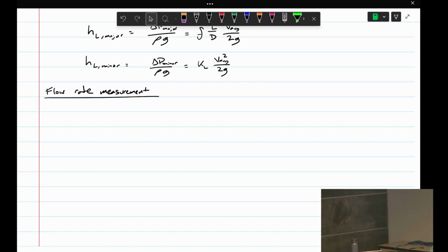Look at the drawings. So that maybe is the nominal case, when you're controlling this. A strain on different parts of the pipe. That's an interesting one. So that could maybe give you the pressure if you had a very good measurement. I think that might actually be used for pressure measurements in some very niche cases. Normally pressure would just be measured with a static pressure tap that we stick a valve on.